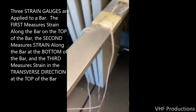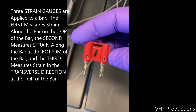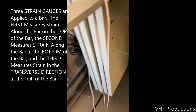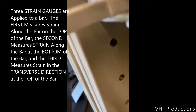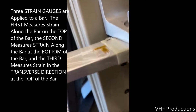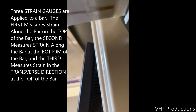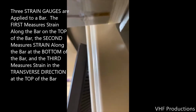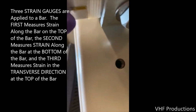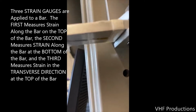The first strain gauge we will be using is oriented so that its long axis, its most easily deformable direction of the strain gauge, is aligned along the length of the beam. This configuration allows us, when we push down on the end of the beam, deflecting it downward, it puts the top surface of the beam into tension, and the maximum tension will occur back at the hinge point on the top surface where the strain gauge is mounted.